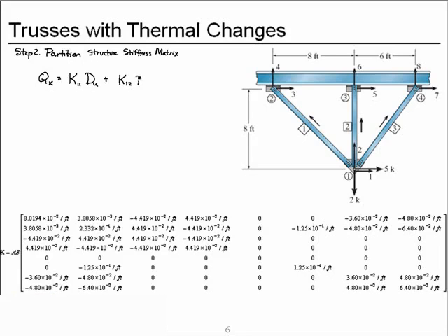And so we multiply that by the known displacements, which are the displacements at the supports, and in this case those are all 0. There are no support settlements, and so this chunk of the matrix will be multiplied by 0, and this component then equals 0.